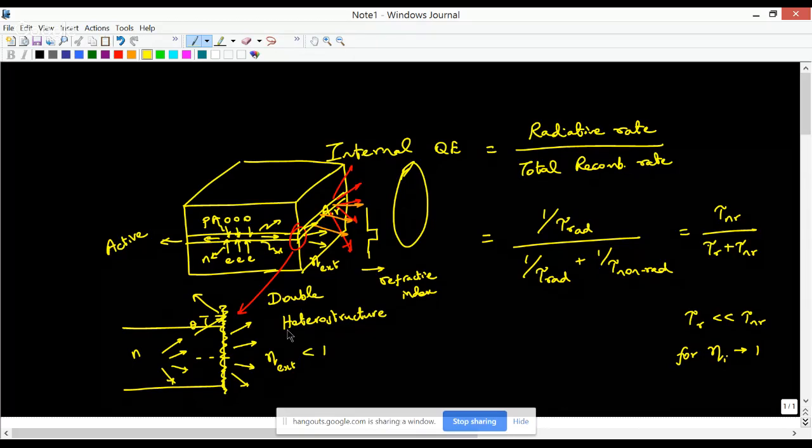And then another question is, what happens to the phonons that are emitted in the indirect band gap semiconductor? So phonons are essentially vibration modes in the material. So if you have an indirect band gap semiconductor, we said any transition from the conduction band to the valence band would have to be aided by a phonon, and a phonon is essentially a vibrational mode.